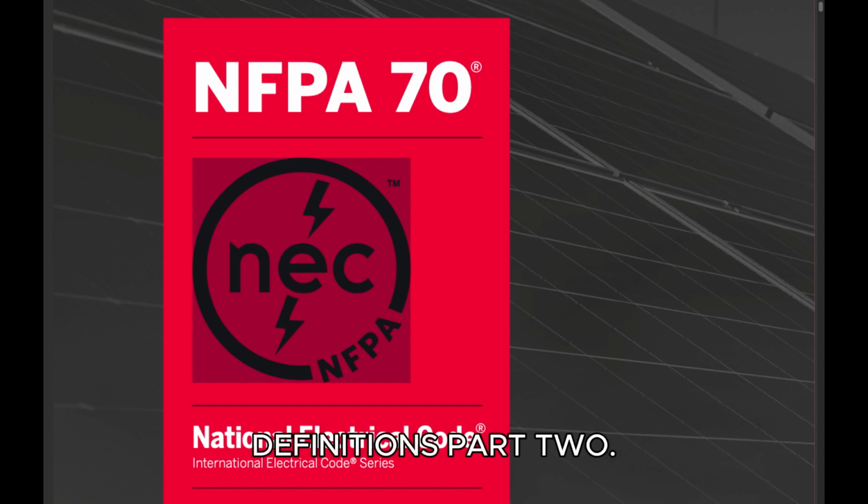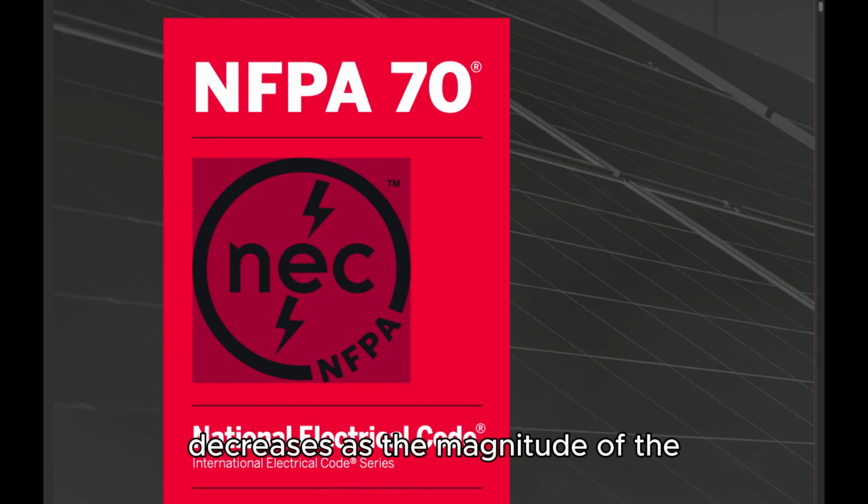Article 100 Definitions Part 2. Inverse time as applied to circuit breakers. A qualifying term indicating that there is purposely introduced a delay in the tripping action of the circuit breaker, which delay decreases as the magnitude of the current increases.